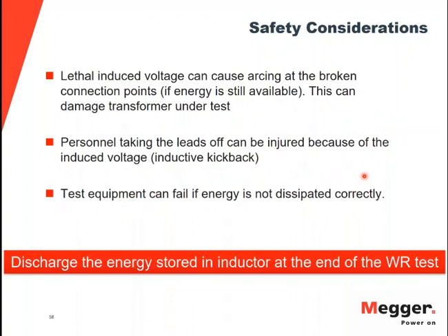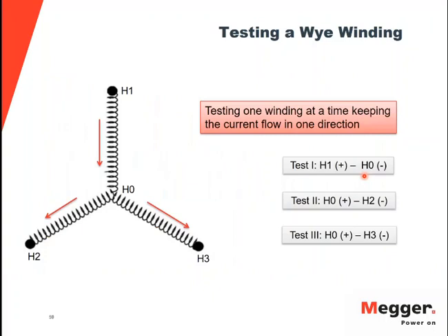And as I mentioned, you should discharge the energy stored in the inductor before you take the leads off, and that is very important from the safety point of view. Now let's talk about the efficiency.